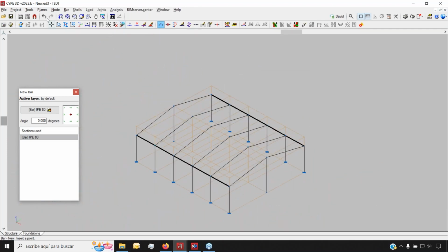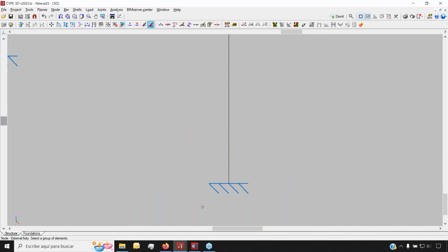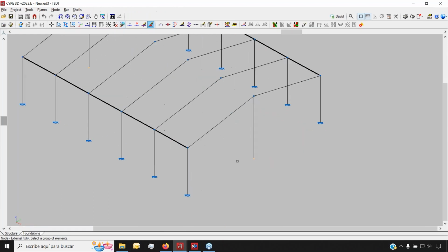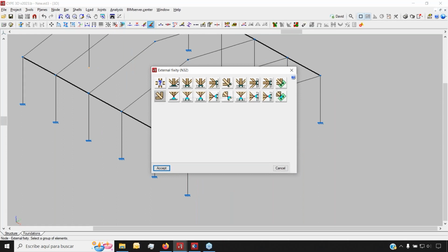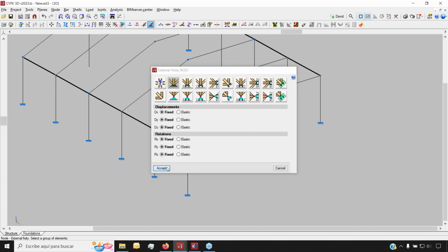And I'm going to set up the fixity for these nodes as well. You can see that before we've set it up so that the different nodes here, the different meeting points with the ground, are fixed nodes. But if we want to, we can even work with many of the different fixities that we have here by default. So if we want a pin connection, or if we want a roller right here, or in this case, a fixity, that's something that we can customize as well.